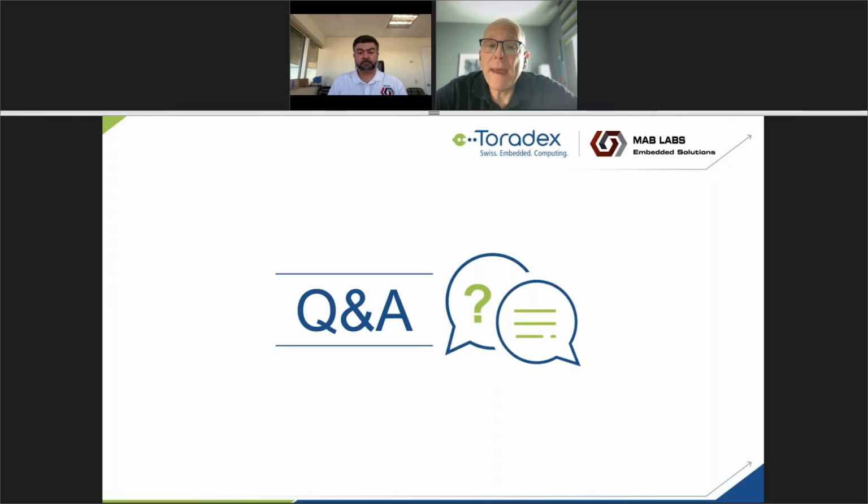I know that in the past we have had support for FreeRTOS, and there's a lot of community ports of various RTOSs. In a lot of cases, they may not directly support, say, the actual Toradex module, but you can configure them for the generic M4, M7, whatever is on the SoC. So if you have another RTOS that you particularly like, it should be possible to get it up and running. You might have to jump through some hoops as far as disabling things in the Linux device tree to make sure they don't conflict and that kind of thing, but definitely should be doable.